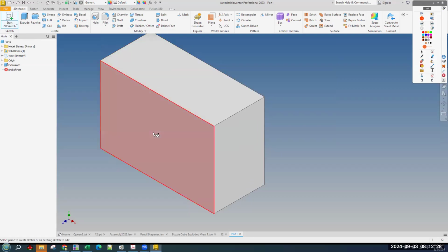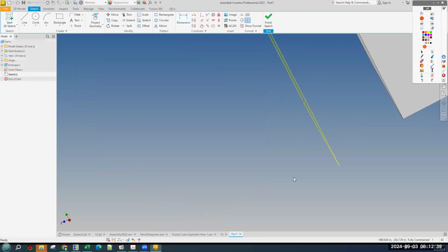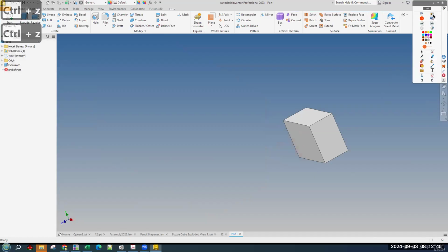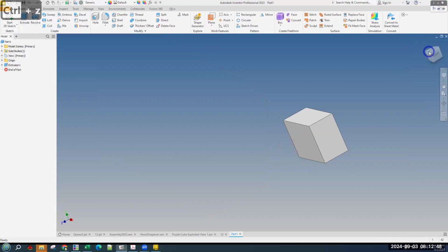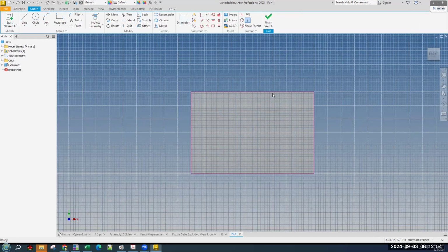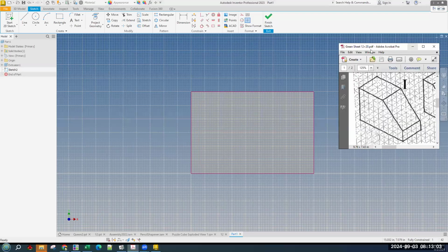And we want to sketch on the front. Okay. This, you need to do a full click. If you click and drag, it will try to give you an offset plane, which is not what we want. We want to be sketching directly on the surface there. Okay, so that's not what we want. What we want is just sketching on the front, which is here. Okay, and because you have auto project edges for sketch creation and edit, it draws the outside line, which is super useful. So now we just need to draw the line that makes this shape,